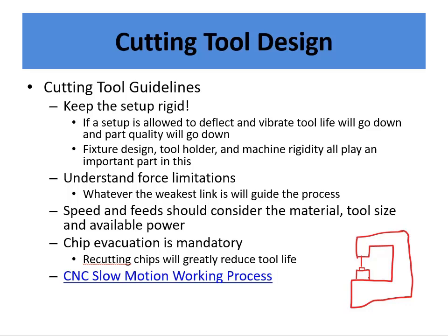That whole setup needs to be super rigid, right? If there's any slop or any movement between the parts, then you're going to have some issues, and you're going to have vibration, you're going to have movement. So the instant in time where that tool is engaged with the workpiece and that chip is being formed, rigidity comes into play and is very important.